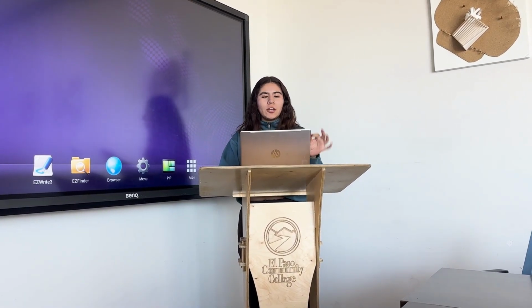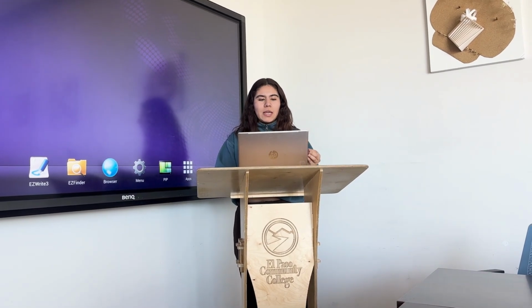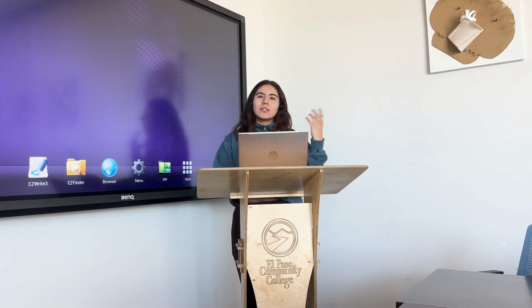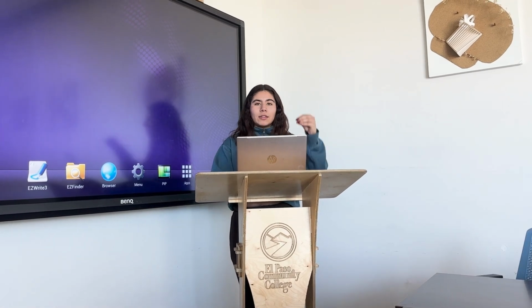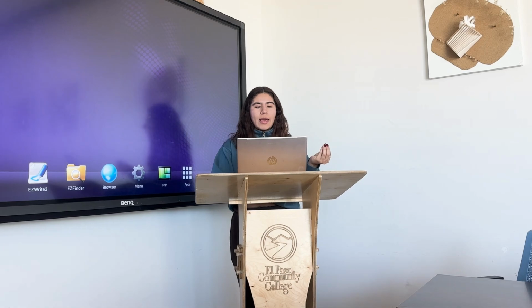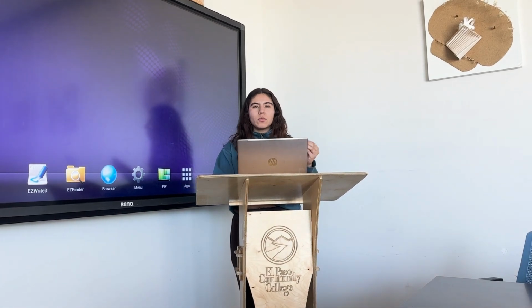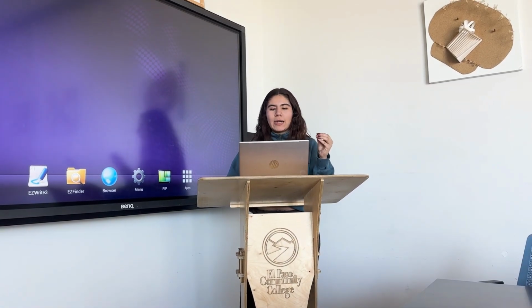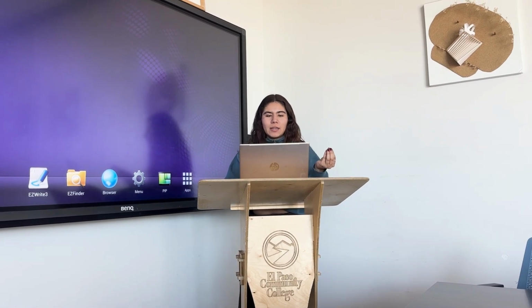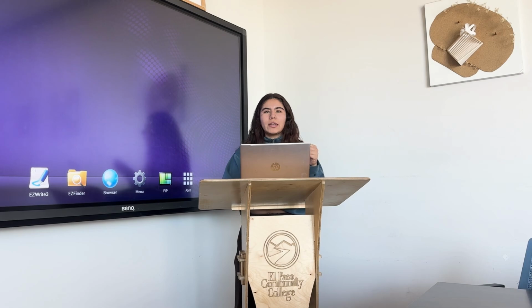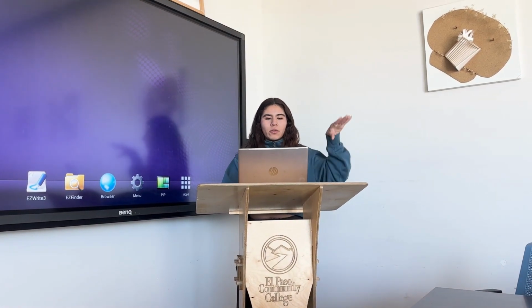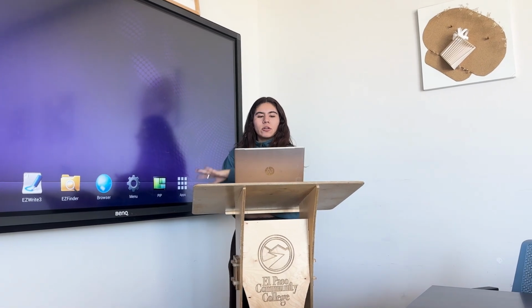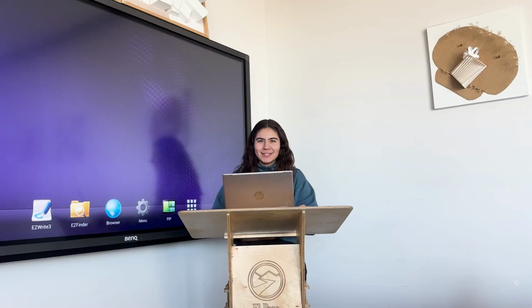So metal coping at the top of a masonry parapet is one example of an external flashing. It acts to prevent water from entering the wall at the highly exposed location, and it also helps with the intersection of a flat roof and a wall parapet, which is usually constructed in 2 overlapping parts: a base flashing that is part of the roof membrane and an external metal counter flashing.